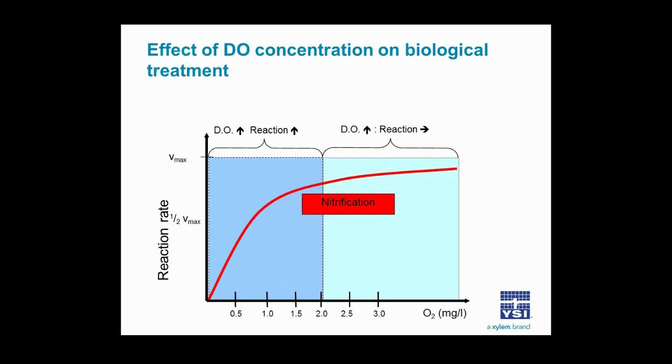And a number we can maybe classify this using is the DO concentration at which the nitrification rate is 1/2 of the maximum rate, 0.75 in this case. CBOD removal, the curve for that is shown here with the black line, and this function occurs with the maximum rate occurring at a DO concentration of 0.3.